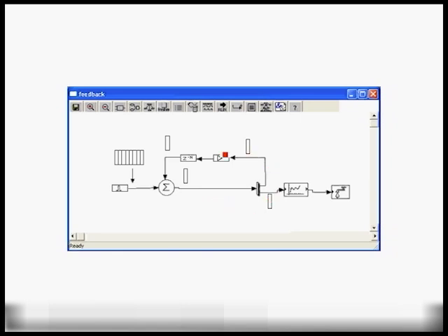If you have feedback, you have to insert a delay. In some cases, delay is part of the actual design. In this case, a simple IIR filter. But in cases where you do have feedback, you have to insert a delay. The delay block is special in the sense that it will actually output a sample even though it has nothing on its input in the initial visit, and that kickstarts the simulation and gets you out of deadlock. So that's how you handle feedback. It's very efficient and it works like a charm. We'll see that in the next example.